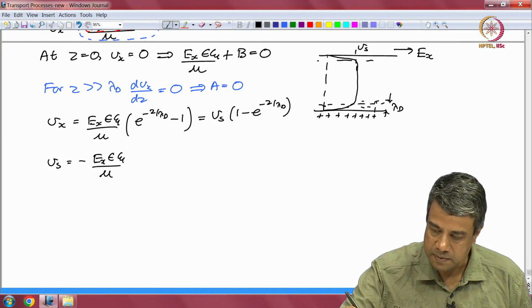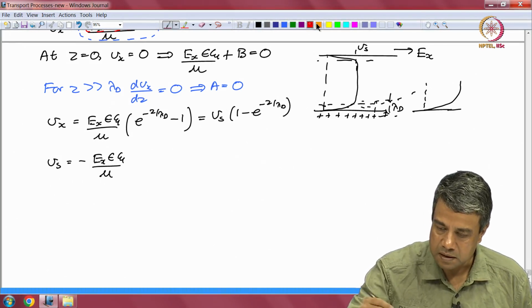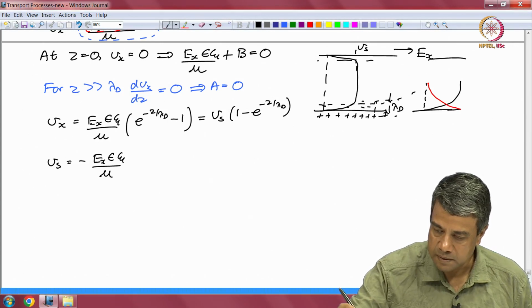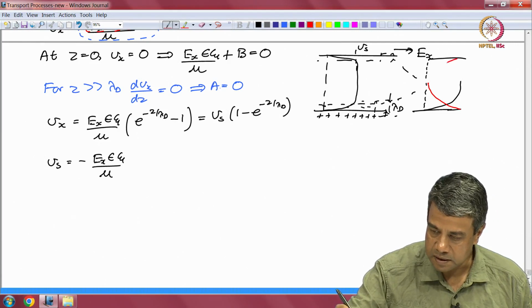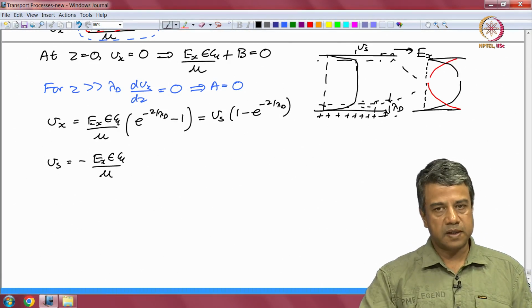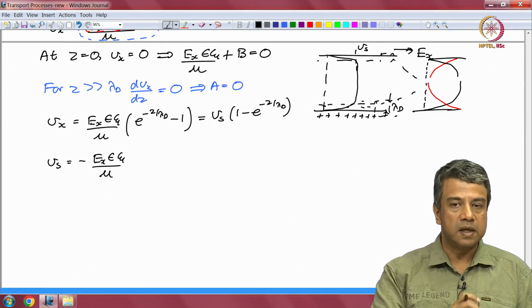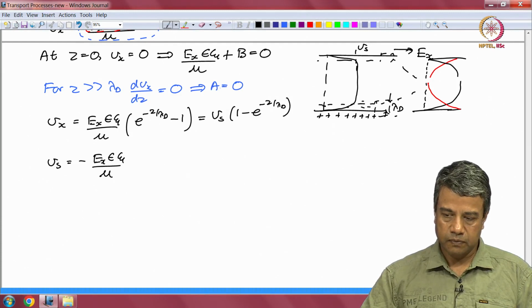So, I had basically expanded out this region, where I got the slip velocity going like this and the charge density going like this. Symmetrically, I can expand it out about this. If I expand out this region, I will have a similar expression. In that case, the Debye layer thickness will decrease like this and the velocity will increase like this. It is a symmetric configuration. So, you have a slip velocity at the center and you have two regions where the velocity decreases to 0, where there is force density due to the charges on the surface.